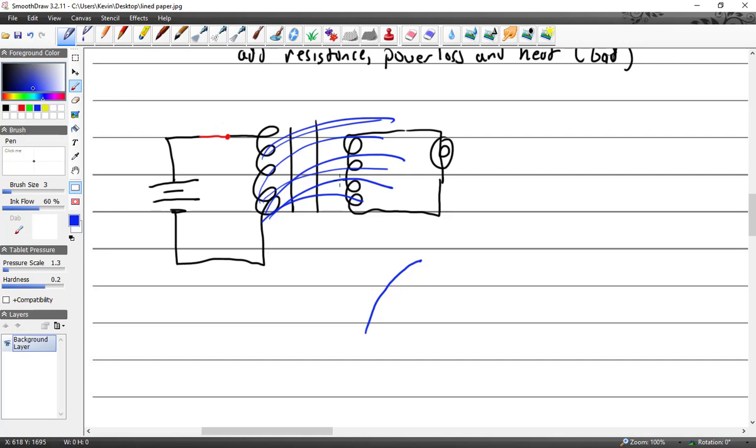So as it's cutting across the secondary, you can expect to see this light go because we're going to transfer energy. But because it's DC, it's going to build up and do what? Just stay. So as it stays, the magnetic flux is there, but it's not changing. There's no change. You must have change. It's stagnant. So it's built up, it's stagnant, so nothing happens.